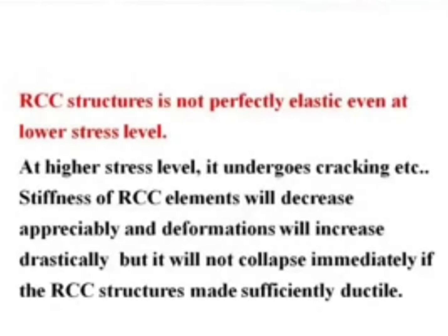But if the stiffness of structural elements decreases, how much has it decreased? In the recent code, they are saying that when you are going for earthquake analysis, then the beam stiffness should be reduced to a particular level.